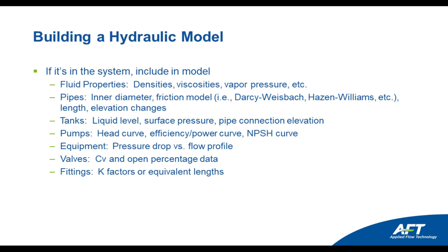For equipment, there are a lot of different ways that you can model the hydraulic behavior through different pieces of equipment. In general, one of the easiest ways is to just model a profile for your pressure drop versus flow, and that'll do a good job at capturing the hydraulic behavior. For valves, you can model CV values and include open percentage data.